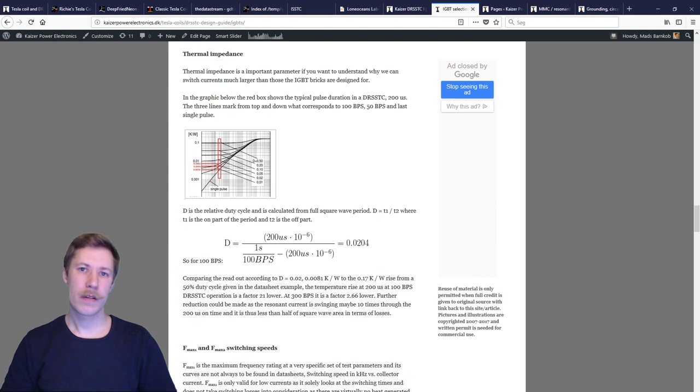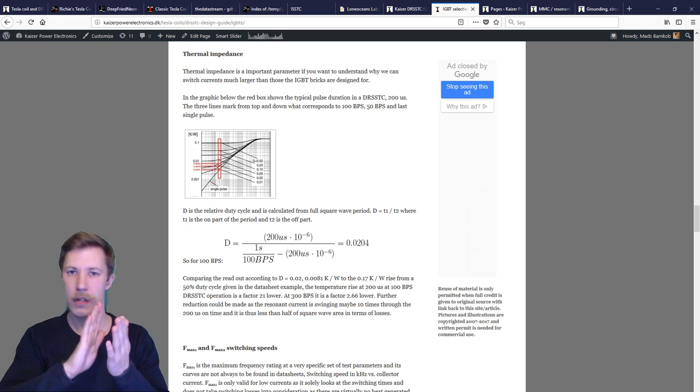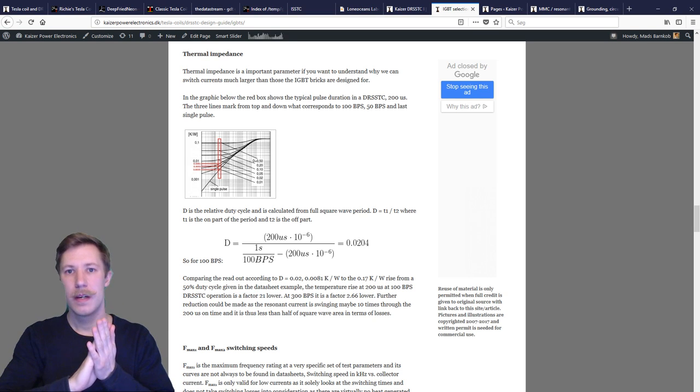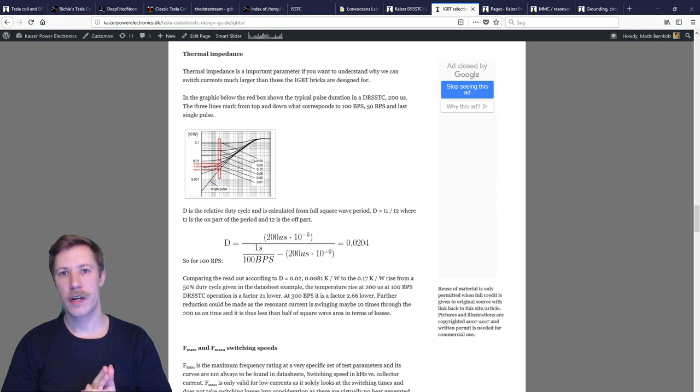It's all about bus inductance. Here it is important that you design a really low inductance bus, that you have your DC bus plates all parallel to each other, one big plate even covering the terminals. You must ensure that your current sharing from the DC link capacitors is shared evenly, that you have the same length wires from your rectifier bridge to the IGBT bricks.